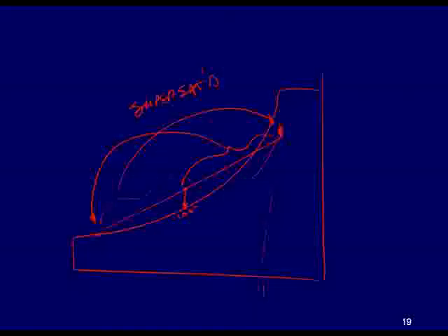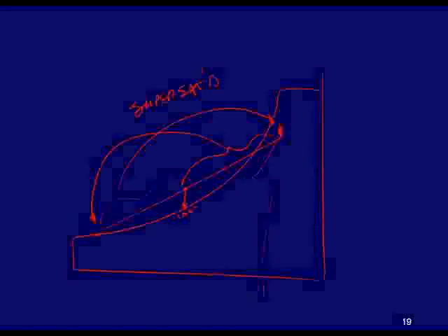And notice that this is our saturated line of 100%. If when you mix the two together you wind up outside the saturated region, at what would be greater than 100%, we call that supersaturated. And of course it would have to condense to get back to saturation, so you'd have to drop out this amount of water here, this delta omega, to get back to saturation, and you would have dew forming or rain or some form of precipitation.